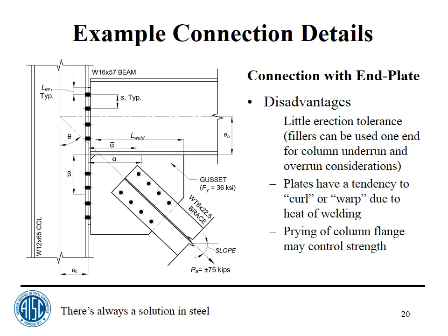one of the jobs that we did where we had a couple of power plants, we convinced the engineer to use shear plates instead of double clips, and the uniform force method, and what has been dubbed special case 4 in this presentation. And we saved, according to the engineer, not according to anything that I've said or my employer has said, but rather the customer said that the job came in $2 million less than what they estimated it to be, and he attributed that to the things I mentioned 2 weeks ago and 3 weeks ago.